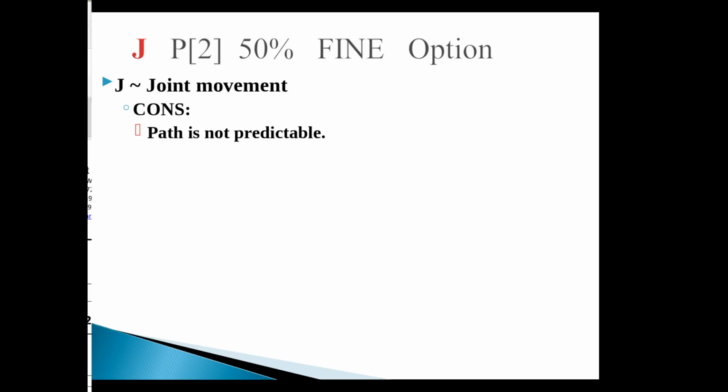Okay, so one of the things we've got to remember there is, since we don't really know what that path is, because as we speed up the robot or slow down the robot, that path may change. So when you're testing the robot, remember that when you're in teach mode, the robot can only move that tool center point 250 millimeters per second.